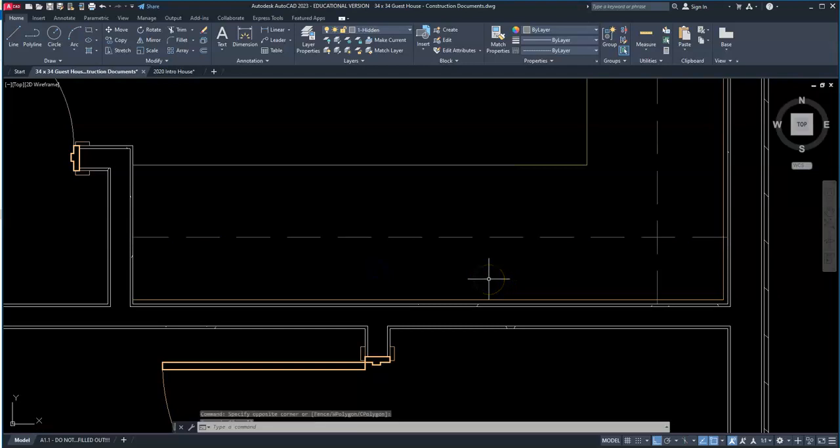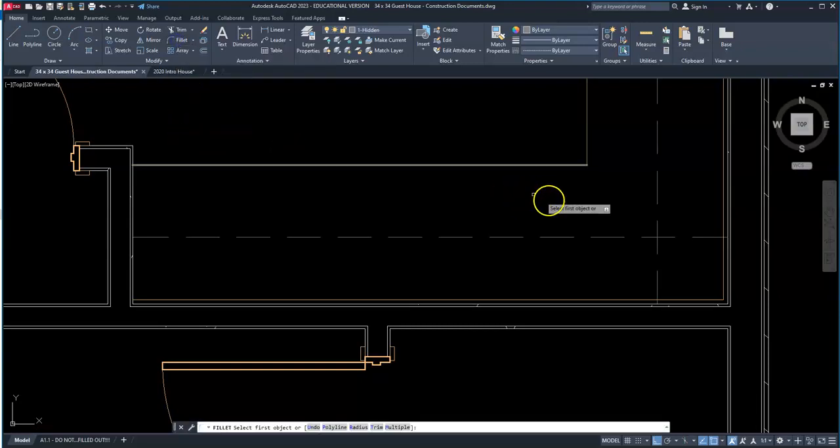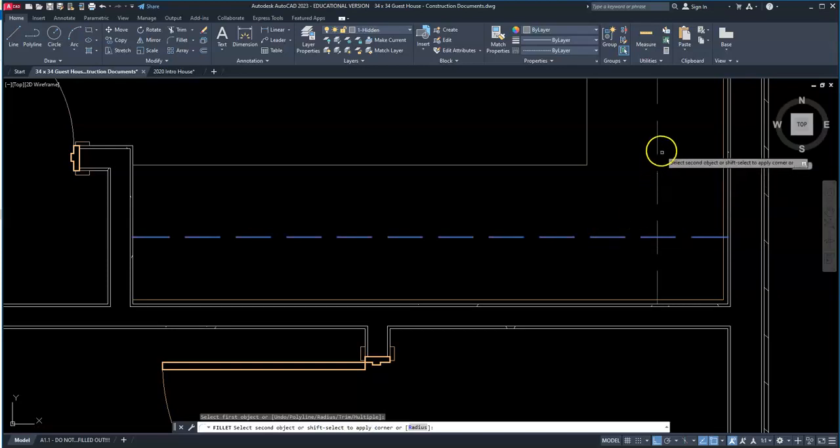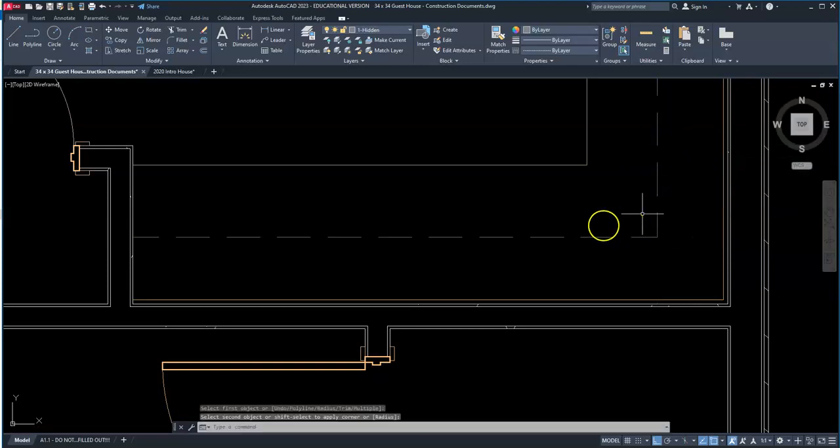All right. Now you'll notice on your floor plan that these lines over here are not supposed to be crossing because we don't have cabinets intersecting each other. So we're going to use the fillet command, which is just similar to Revit. We're going to click on the fillet and click on the first line and click on the second line, and it merges the two together.